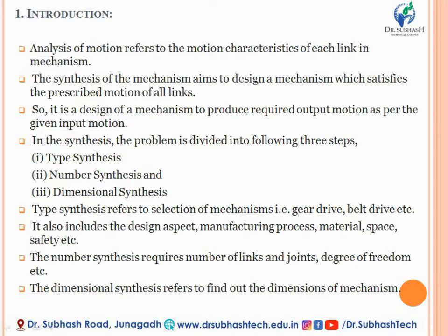Suppose you select a slider crank mechanism and you require some output motion, so how many links and joints do you require? Number synthesis determines the number of joints as well as the number of links.